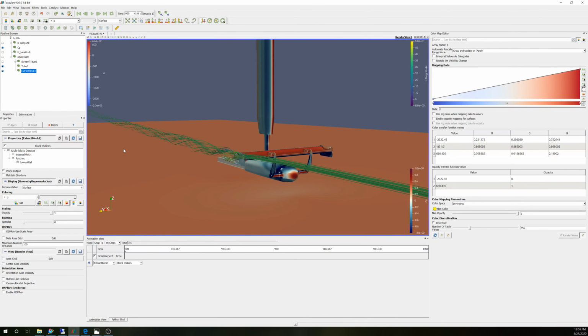Normally if you're using ParaView and you already calculated CP, it would already have it, but I pulled in the model because I break these up using VTK, so that whole thing's a patch. It makes it easier for post-processing. I didn't do the lower wall, so I will run the same equation so you can see what the pressure's like on the actual floor.